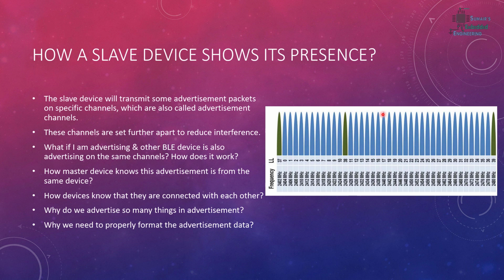So basically there is a special time limit, and we can set this time limit to a couple of seconds or maybe many seconds, but normally it's just 3 or 4 seconds, so that our disconnection time is good. For example, if our device disconnects, then within 3 or 4 seconds the master device knows, because after 3 or 4 seconds it's going to transmit a connection interval request, and then it's going to read it, and then finally it will see if the device is connected or not.